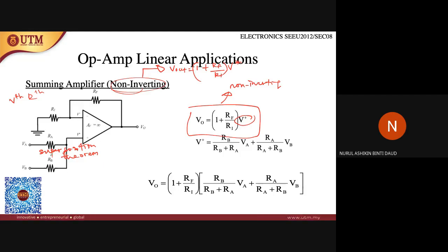You replace the multiple linear resistances with R Thevenin, and the linear voltage will be V Thevenin, right? But for the superposition theorem, we use it when the linear circuit has more than one source. So you have to assume that only one source can be used at a time.